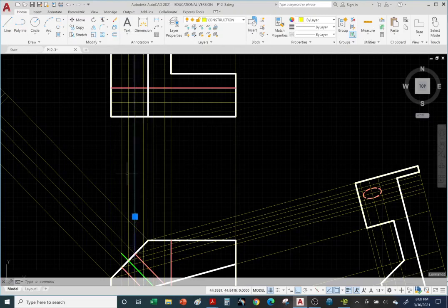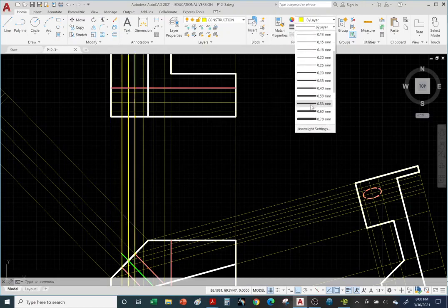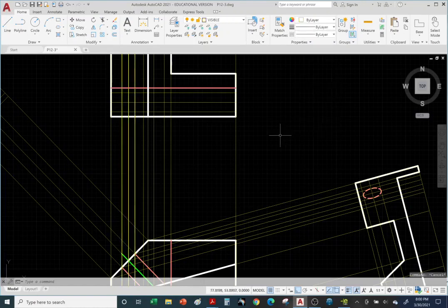These construction lines and this construction line will define our center mark and our diameter for the hole, our quadrants. Let me make these a little bit thicker so they stand out. Okay, there they are. Hit escape to deselect.